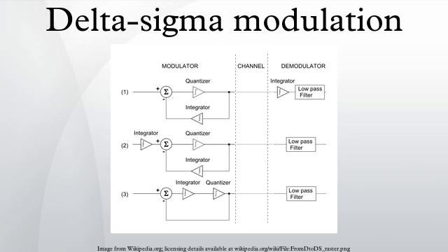In a conventional ADC, an analog signal is integrated, or sampled, with a sampling frequency and subsequently quantized in a multi-level quantizer into a digital signal. This process introduces quantization error noise.